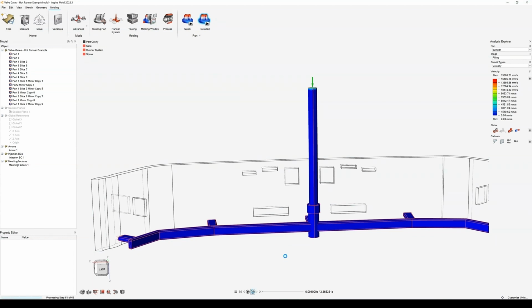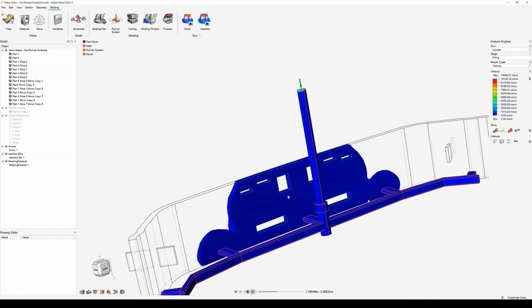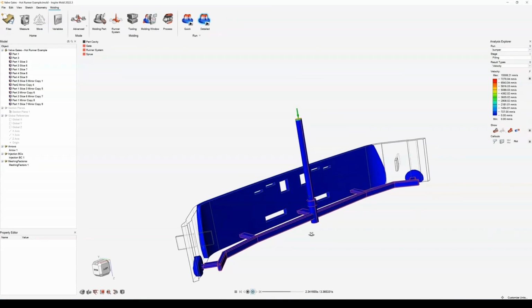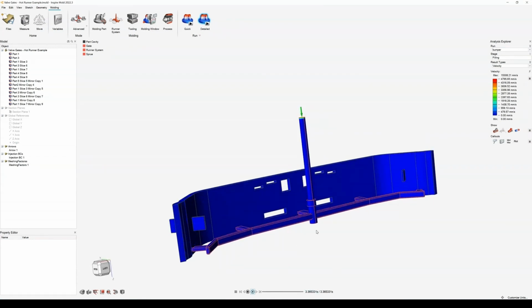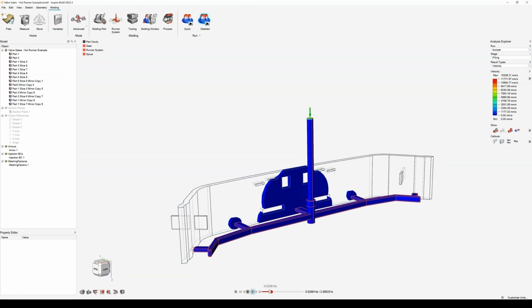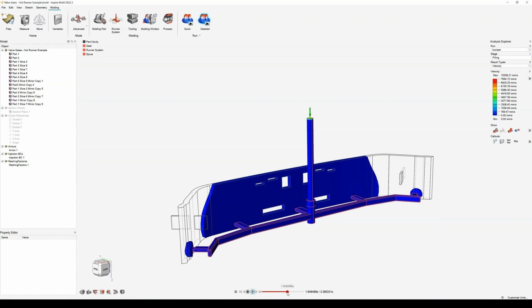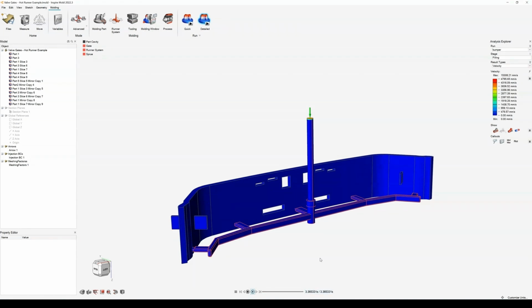what we're going to see here is initially the valve in the center opens and lets material in. Then the next two open. I'll go through this a bit slower. Then these two open, and finally when the flow gets to a certain point or a certain time, the other two can open. So that's just with valve gates. We can do hot runner systems.